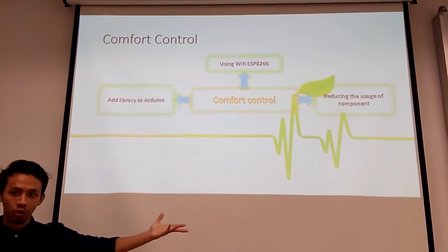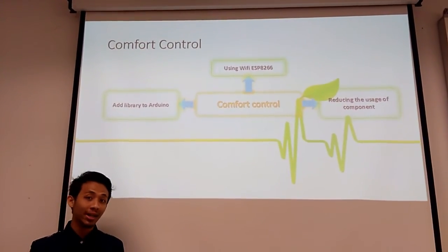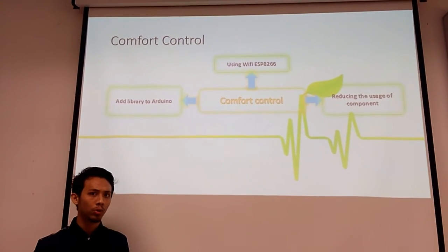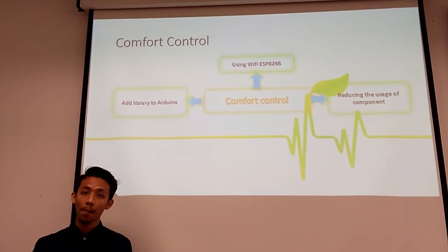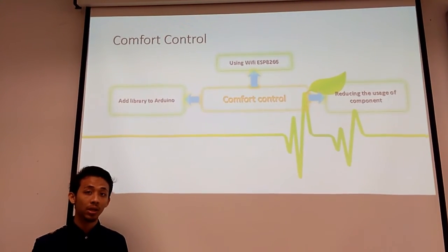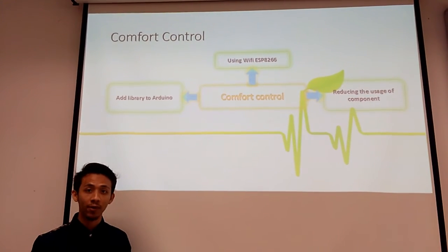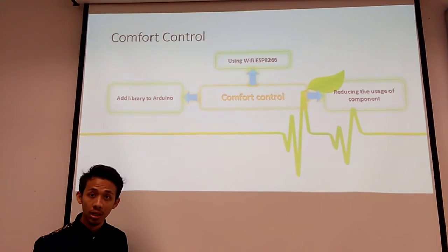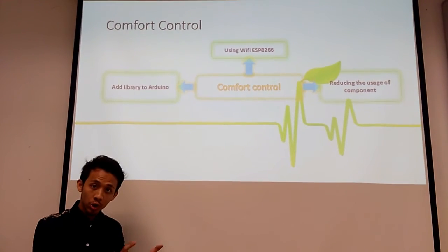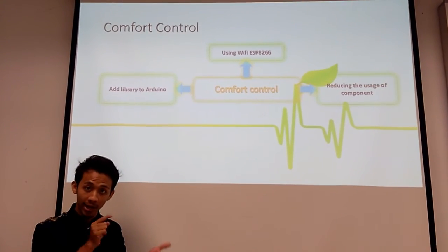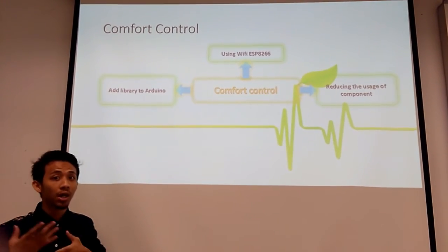Okay, next are the suggested solutions to solve our issues. For comfort control, just before I mentioned we cannot run the Arduino because we lack libraries. What we need to do is add the library to Arduino. For example, Arduino does not come with the library for the LM35, the temperature control sensor. We need to upload the library to our Arduino to enable interface between the temperature sensor and the Arduino.